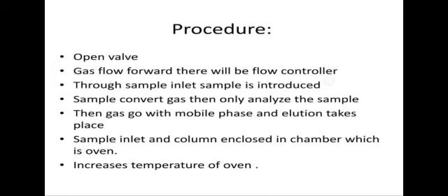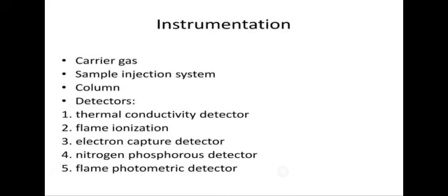First, the carrier gas. Hydrogen, helium, nitrogen, and air are most widely used as the carrier gas. Hydrogen is more advantageous compared to other gases, but also dangerous to use. Helium is the best gas. It is used because of its exceptional thermal conductivity, inertness, low density and greater flow rates, but it is expensive. Nitrogen is inexpensive but has reduced sensitivity.